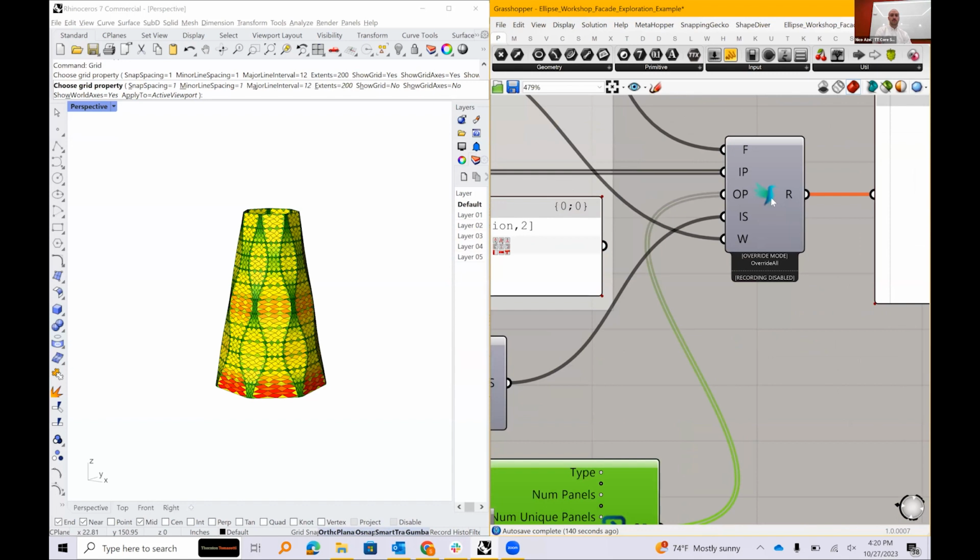Something to note that's really important before you run everything: this is in override all mode. When you run it, it's going to create a CSV file of all of your data. It's also going to create all of the images that it's taken screen captures of. But it can override, which means it'll clean whatever folder you've directed it to, delete everything in that folder and then repopulate it.